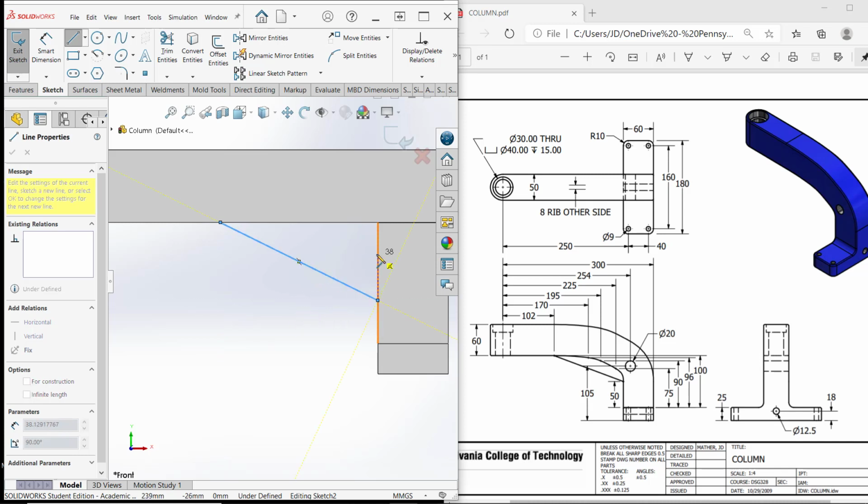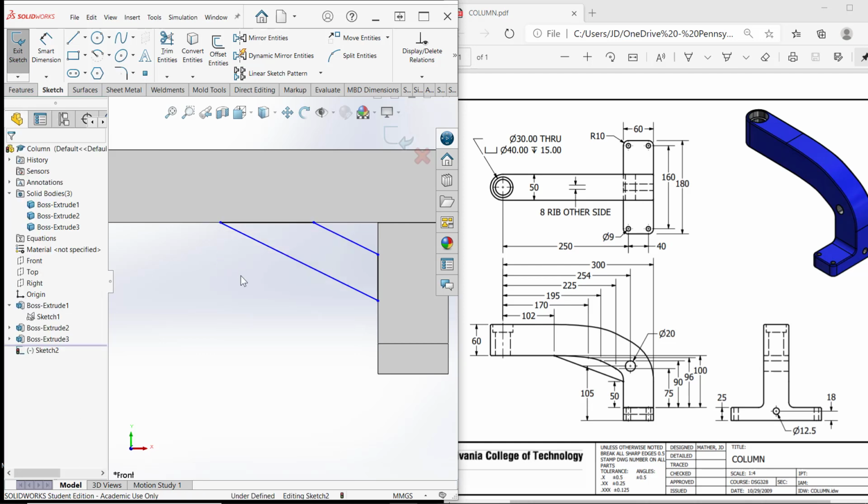And then I'm going to come up vertically, and I'll click about right there, and I want to come parallel to this line. So if you scrub that line, don't click on it, just scrub it. Notice you get what I call a yellow brick road, a tracking line here, that if you come along here, and notice also that it's showing a glyph for a parallel relation. And I'm going to select on this line, and I'll come over here and I'll select it to close that off.